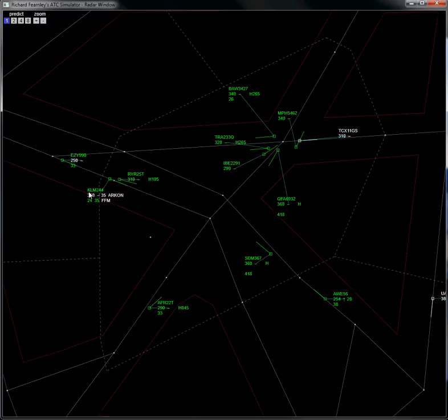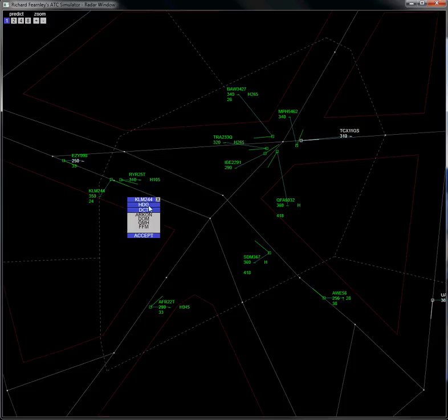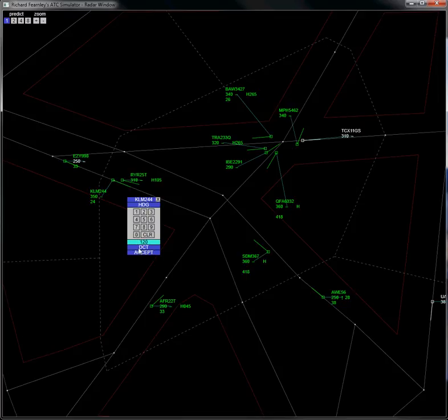Coming back down here, the KLM 244, flight level 350, we are going to turn to the right to split with the Ryanair 25 Tango. To do that, I read he is on a heading of 113, so I'm going to put him onto a heading of 120.